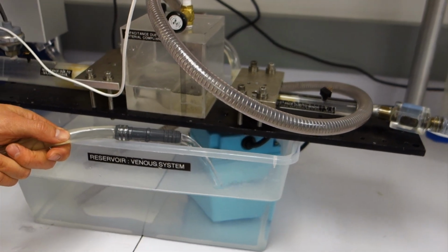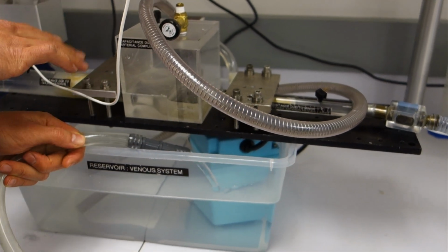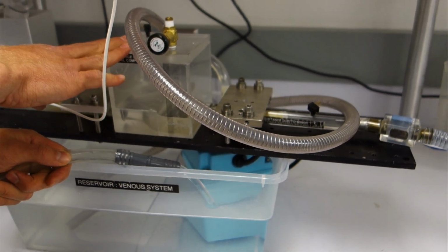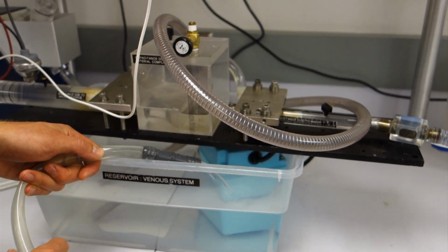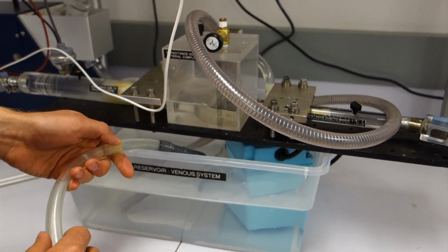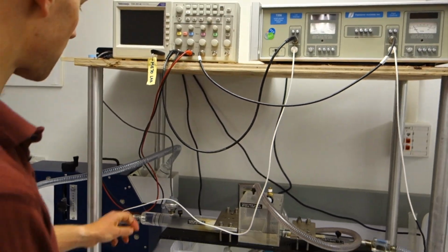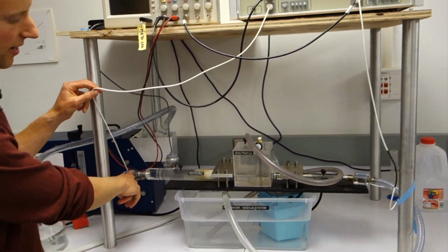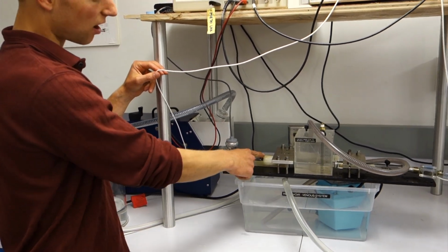So it's modeling the compliance of the arteries via a capacitor, which is filtering the pulsatile signal coming out. And then this is also validated by looking at the sensors. So we haven't turned our sensors on. If you follow the cords coming back from this sensor here, we're going to call Q1. This is going to be flow rate coming through R1.